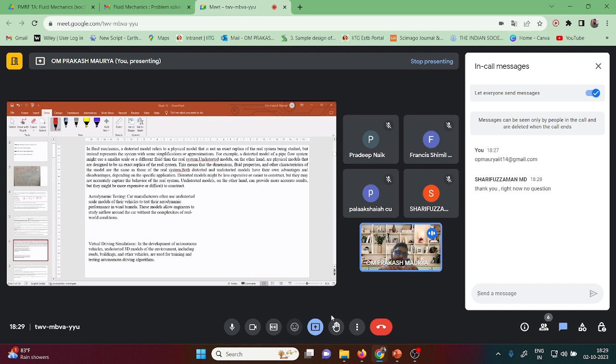Francis, I'm not getting exactly what you are asking, but what I feel you are asking is whether the streamline can be 3D. Yes, a 3D streamline is possible, because the flow can be in the x, y and z directions, all three directions. A stream function is a function of only x and y, not z.